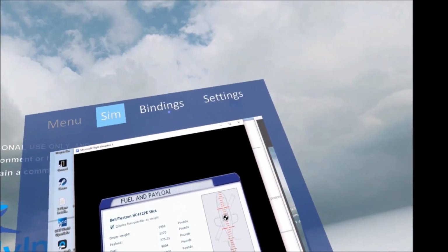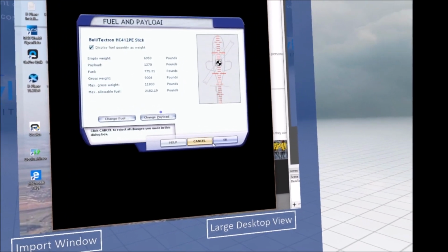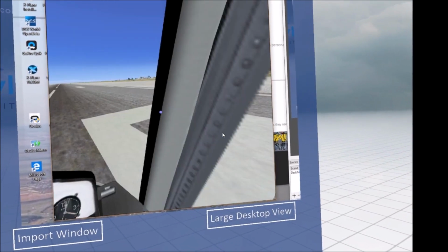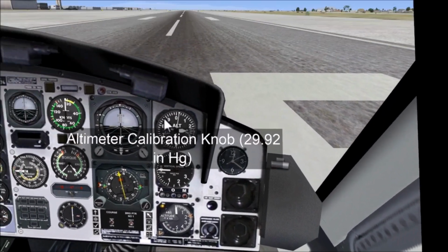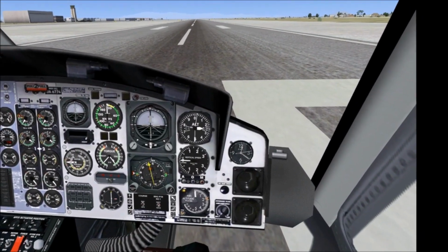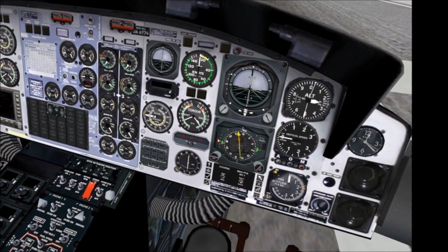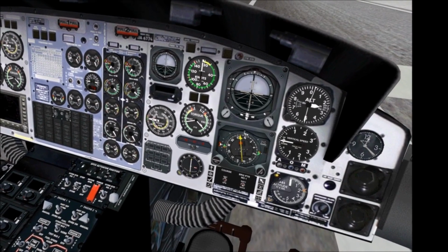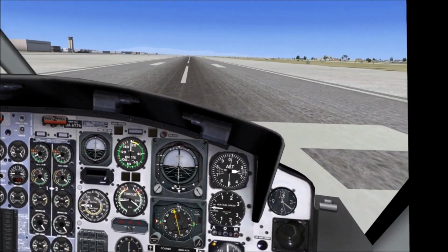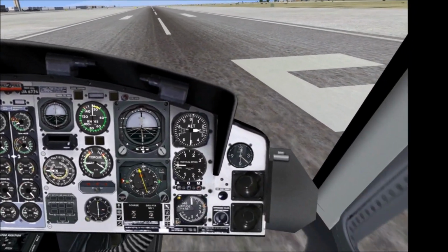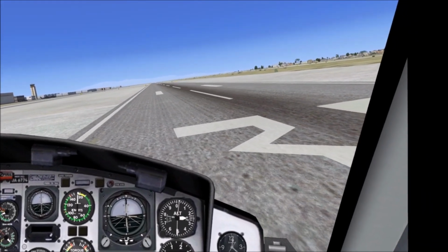Alright, so just for fun, I brought it back down to 9,000 pounds because we had to burn a little gas over earlier. And we're back in, so we're going to keep that same pedal setting that I had for 11,000 pounds. We're going to pick the aircraft up, again looking to see if the pedal requirement changes. We came off the ground at 9,000 earlier in our test today at 27% torque, so we're right at 27%. And pedals are just where they were a second ago at 11,000 pounds, and the nose isn't going anywhere.